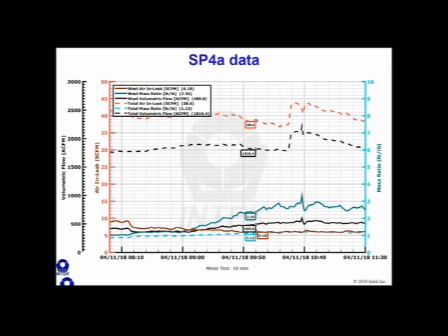And again, I'm going to ask you for your interpretations of this data. So when we arrived, this is the data that we saw. And so I'm going to walk through what the data is. The dashed data is from the revac on the east side, so the east side bundle. So we have red as the air in-leakage value from that east side probe.